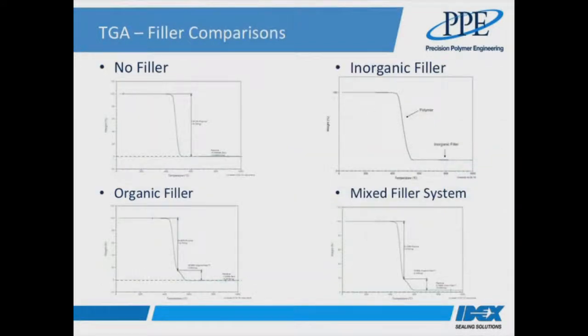So what we can see here is essentially various different TGA spectra for several different elastomer materials or groups of materials. So for anyone not familiar with the technique, thermogravimetric analysis allows us to monitor changes in the material as we increase the temperature at a constant rate. And when I say changes, I mean things like phase transitions or vaporization. The test is basically split, where the first part is done in an inert atmosphere and then switched to an oxygen-containing ambient at a certain temperature.